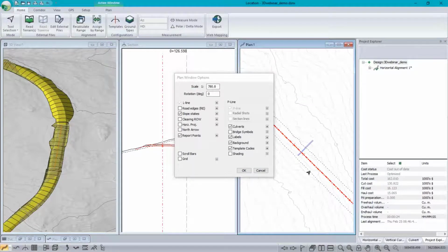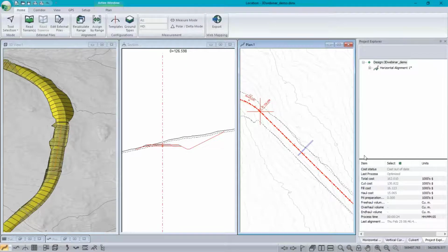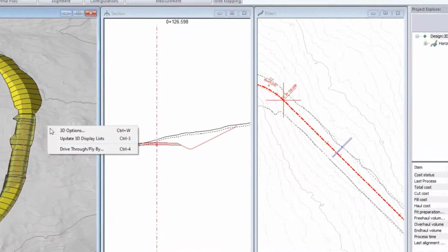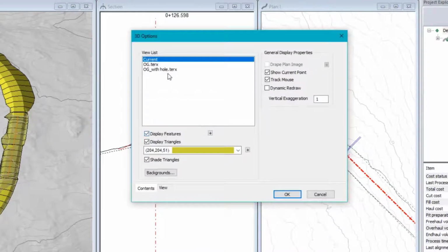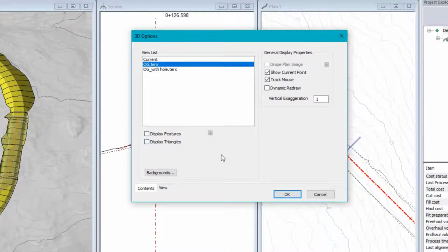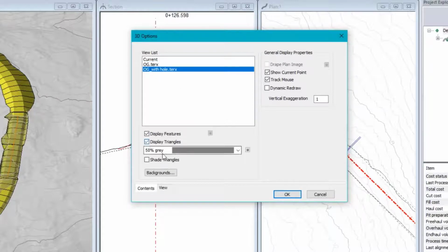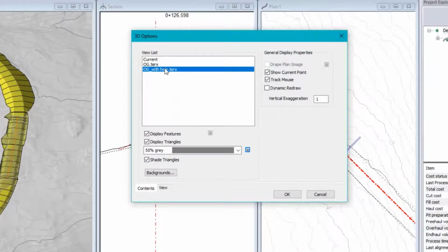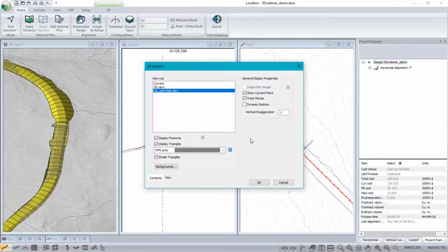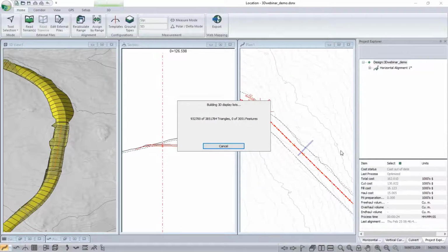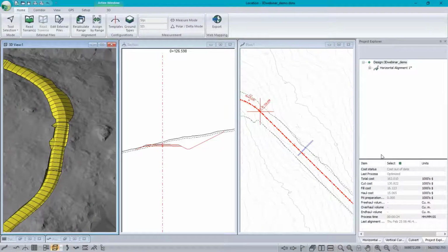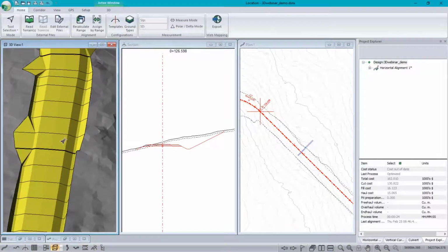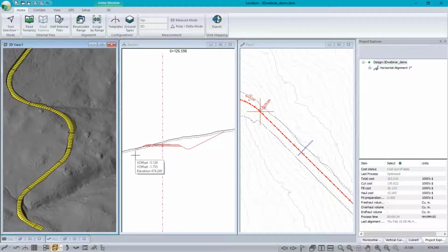Doesn't look any different to the other original ground, really. So it doesn't make much difference in terrain, or pardon me, in the plan window. But here, I'm going to get rid of the original ground, just do not display it, and only display this one. But now I don't have to worry about transparency, so it's fully opaque because it's got a hole in it, the same shape as the road. Oh, this is a different road. That should work. Let's see what it looks like. Actually, it's a different road. I modified the road, but it works right here. It's looking great. Now let's look at the drive-through option.